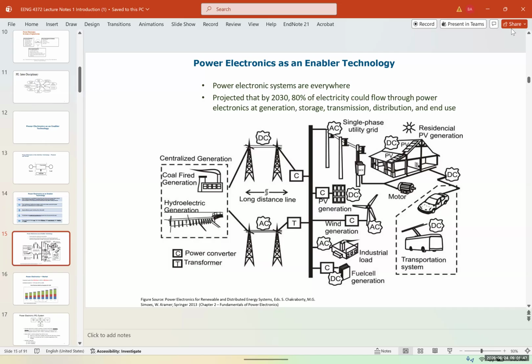Even after that, the battery still will retain like 60-70% of its peak power density. So you can take that battery out. You have a 60 to 100 kilowatt hour battery that's now $500 or $1,000. You can take it out, put it in a container and use it as a grid backup system.